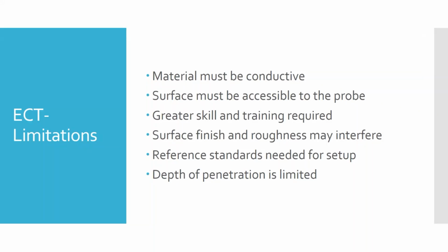And then the last part here, depth of penetration is limited. So it can do surface flaws and shallow subsurface flaws up to about a half inch deep, but you're not going to find anything really any deeper than that. To do something like that, now you're getting into more of an X-ray or ultrasonic testing type environment. So again, this really lends itself to surface flaws or testing things that are thin, like sheet metal.